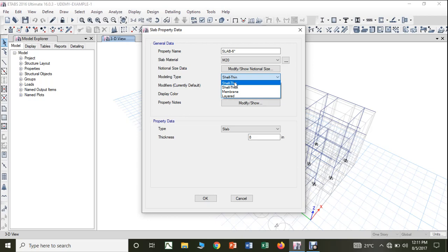Your water tank walls, whether a circular or a rectangular water tank, are not usually built with bricks or blocks. They are made of reinforced concrete sections. There will be hoop stresses due to the presence of water inside, so we have to model the slab as shell thin.